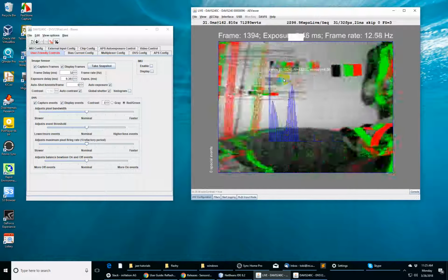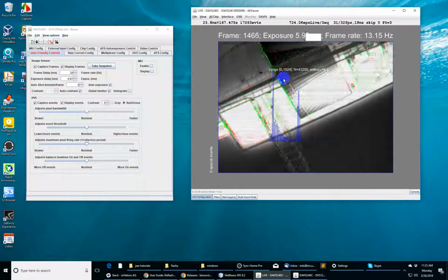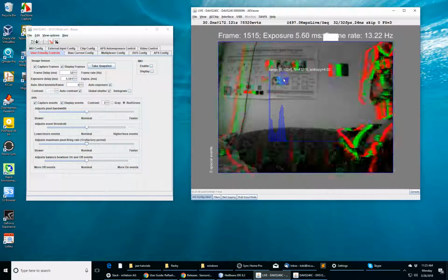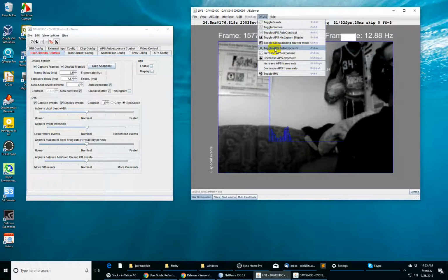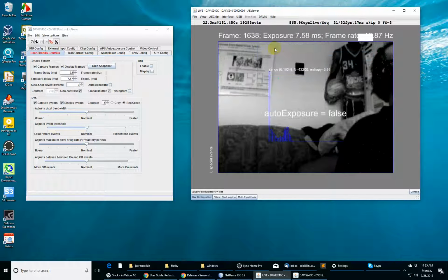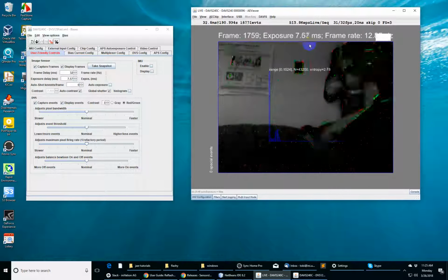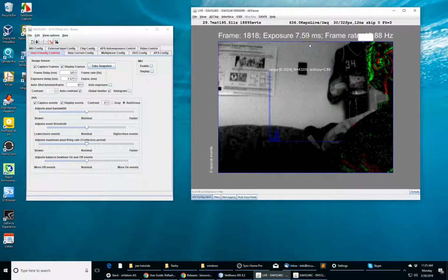You see right now that if I make the image really bright, for example, look at the lights on the ceiling, you get a distribution between bright and dark pixel values. Another thing you can do from the Davis menu is toggle this auto exposure. This is a kind of auto exposure algorithm that sets the APS exposure time. For example, if I stop down the lens, I'll just put some sunglasses in front, perhaps that's easier.